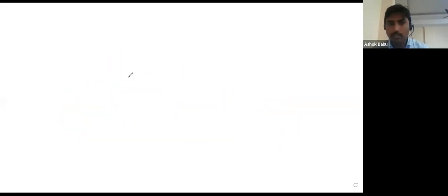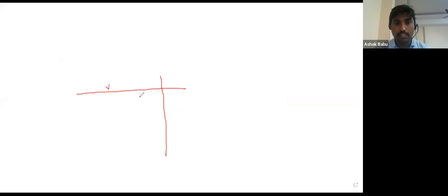Yeah, only draw the reverse characteristics, no need to draw the forward characteristics. Already we calculated the forward characteristics in the LED experiment, right? So in your graph, only take the reverse characteristics. Voltage we take on the negative x-axis and current on the negative y-axis. And for different intensities, when you draw the graph, you get like this. When the intensity increases, the light energy falling on the photodiode increases, and the light energy converted into electrical energy also increases.